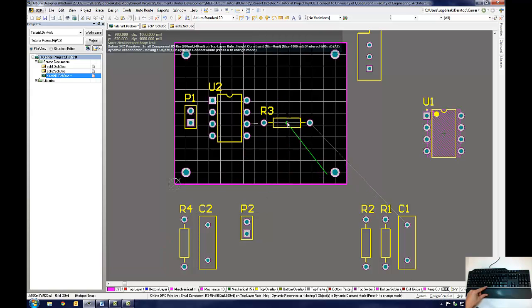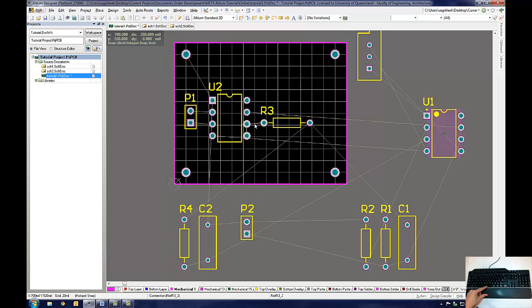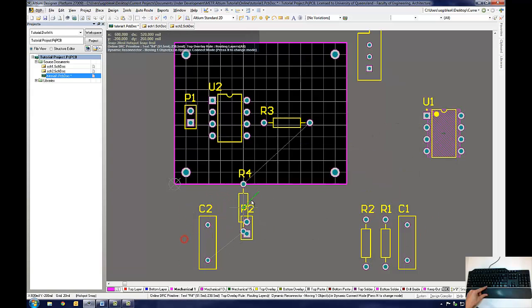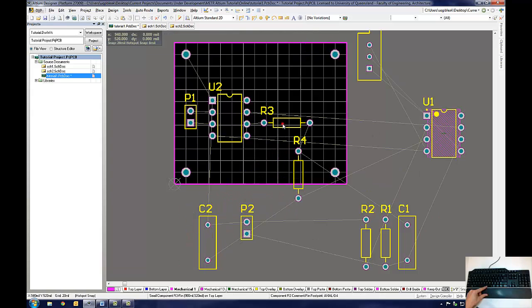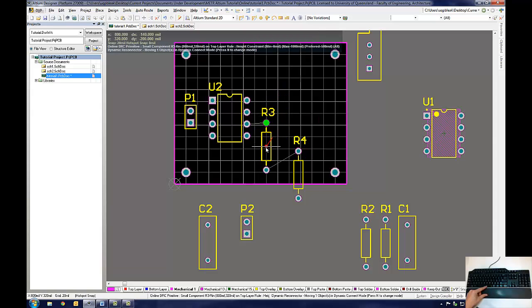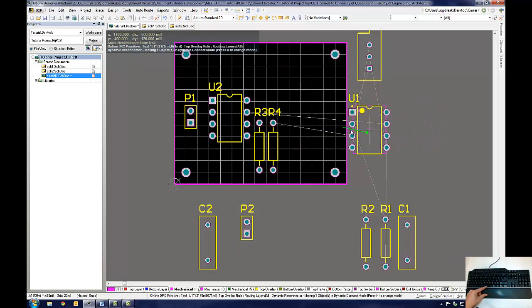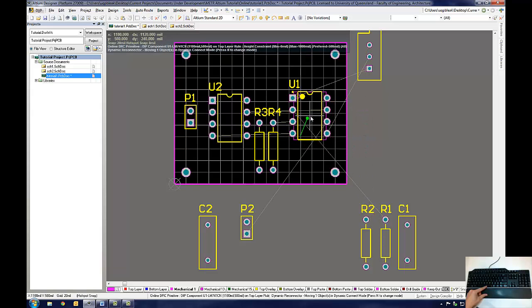Care should be taken to avoid introducing electromagnetic interference into the circuit by avoiding placing tracks and ground planes near noisy components such as coils, oscillators, high-power MOSFETs, and motor controllers. Application notes for critical components often provide advice on how to lay out the components and include information on distances and spacing.